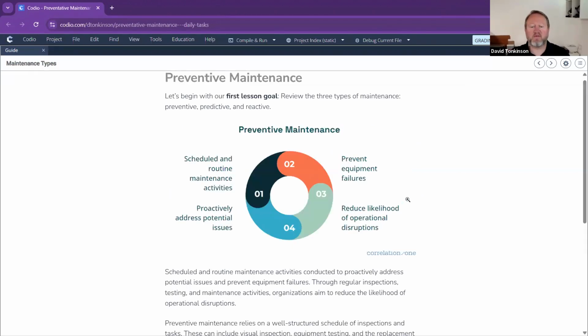The first one we always talk about is preventative maintenance. All these types of maintenance run on a bit of a plan, so to speak. The general idea within preventative maintenance is that you're trying to find things before they happen. These are things we can put into a schedule. So we schedule to look at things, to change things, and to make sure things are running properly at a particular schedule. That's what we're looking for in preventative maintenance. We will find something that might be going wrong before it happens, and this is without receiving any warnings.